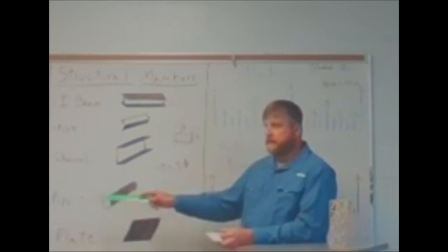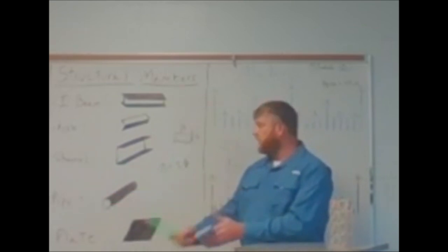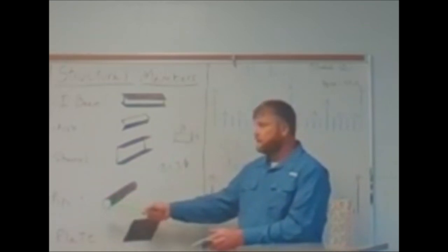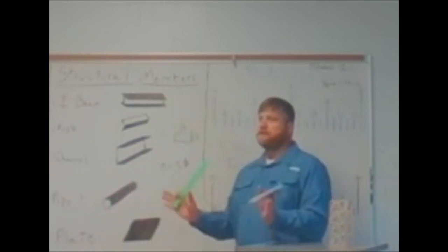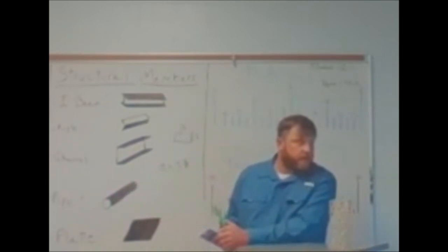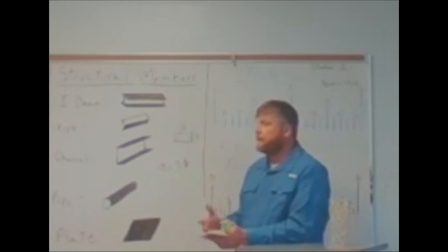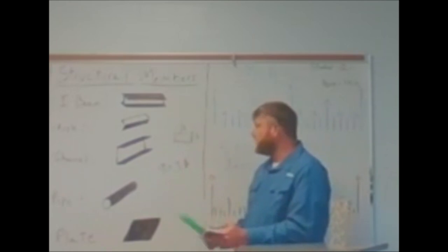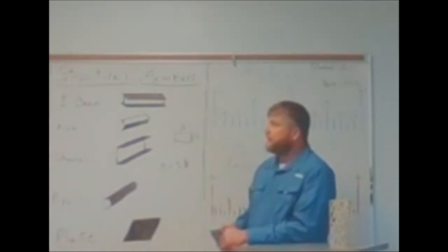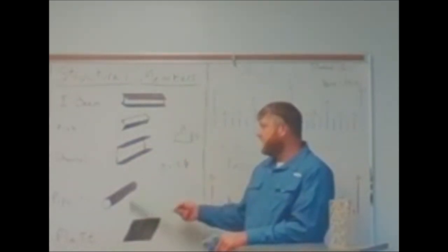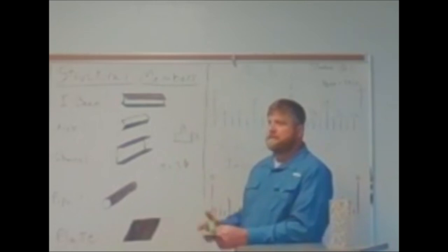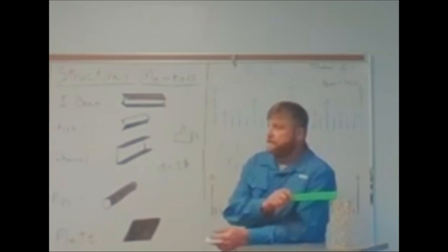With pipe, you bring it in and you weld plate to the end of it, and then you bolt it or attach it to a flat surface structure. That's not very economical. So even though pipe would be very useful to counter structural forces, it's not very easy to build with. So ease of construction needs to be a key factor in your design also.